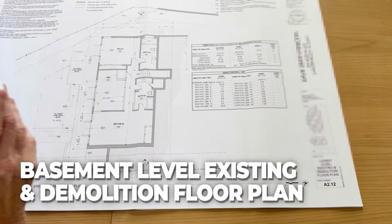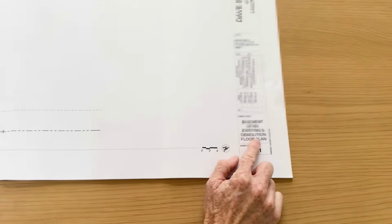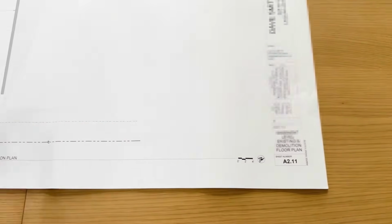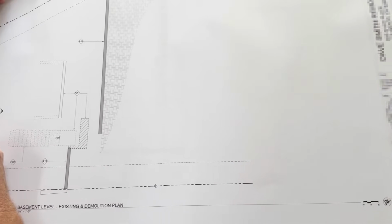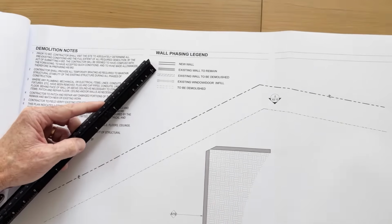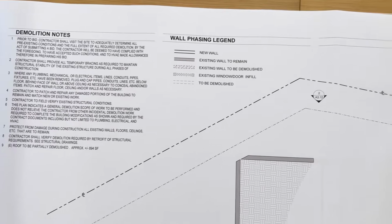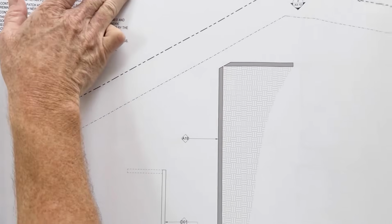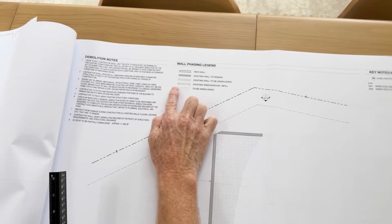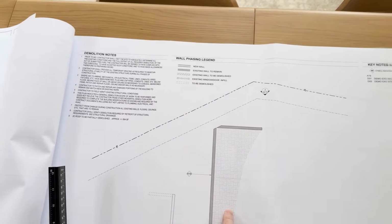So now we're getting into demolition, okay? So this page here is demolition, okay, which is very, very important. So we've got an existing and demolition floor plan. Key here is usually what our architects are gonna do is they're gonna create a wall phase legend, or a legend that indicates what these wall colors and hash marks mean, okay? In this case, for example, anytime we see this condition on the plans itself, this wall is going to be demolished, okay?